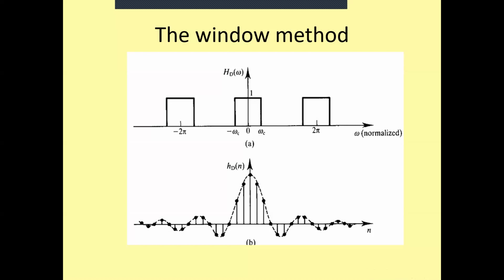You have studied the Fourier transformation in the second year class, and you know, when we talk about the Fourier transformation of a rect function, its Fourier transform will be a sinc function, okay? And here again we have a rect function. So the output will be a sinc function.